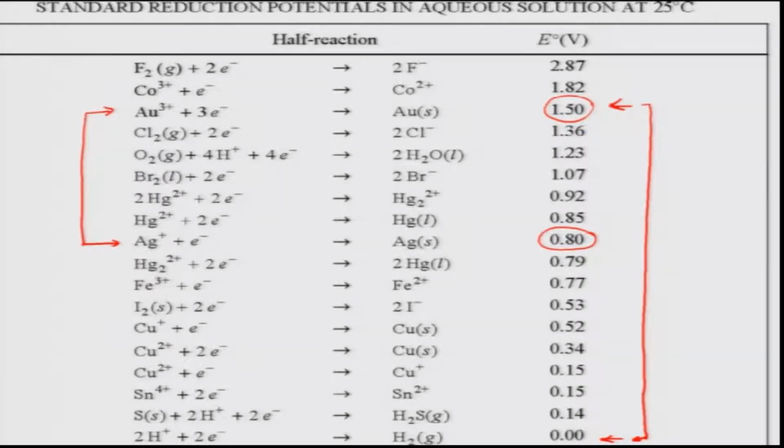Now, if you have a gold silver alloy and dip it in an acid medium, gold will remain, silver would dissolve, and then we can have a porous gold structure, and those pores could be in the nanometric range. That is what we call a nanoporous material.